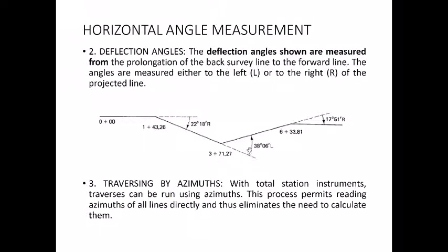Now, in this case, the deviation was towards the left of the original path, so that's why you denote it like this, whereas previously it was denoted like this. That tells you about the direction of the deviation, or direction of the deflection angle. They are really useful in setting out roadway projects or railway projects and similar projects.